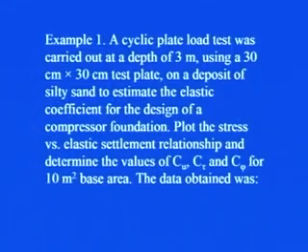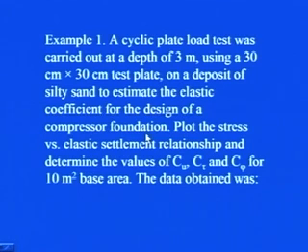The statement of the example is that a cyclic plate load test was carried out at a depth of 3 meter using a 30 centimeter by 30 centimeter test plate on a deposit of silty sand to estimate the elastic coefficient for the design of a compressor foundation. In the last class, when we were discussing the salient features of the three types of machine, we saw that a reciprocating machine is to be used for a compressor foundation. So here we have to design a compressor foundation, and that machine will be a reciprocating machine.